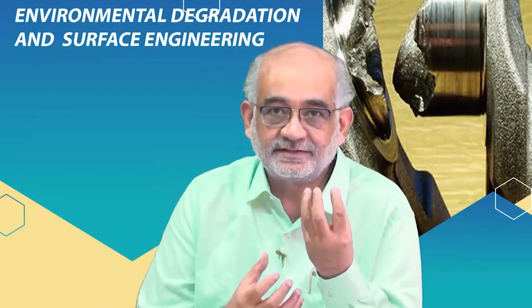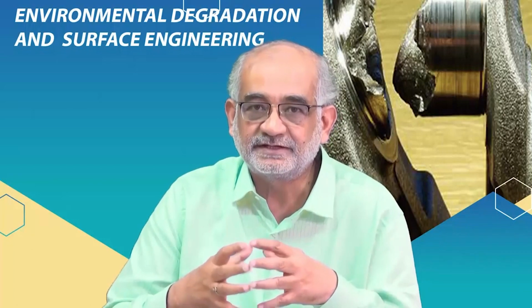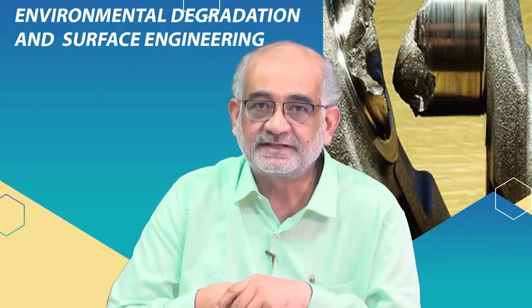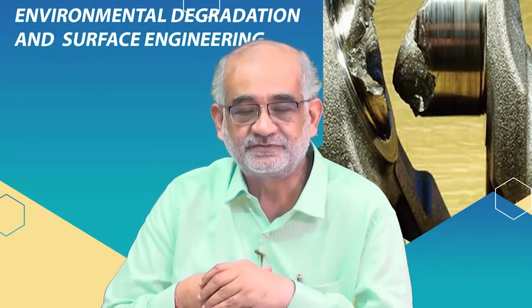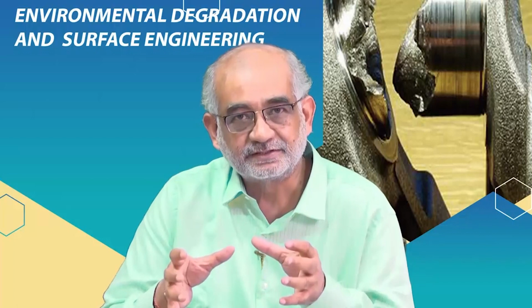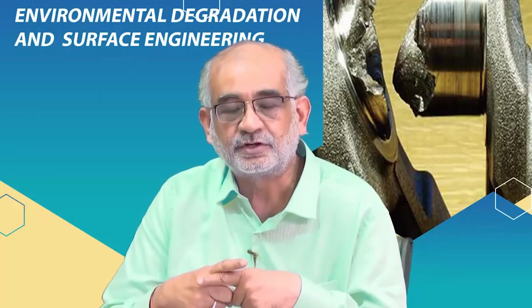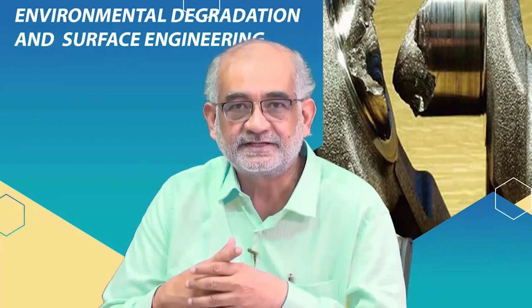So there the structure, the pole has to be of metal because you require certain engineering properties like strength and toughness and durability and so on, and also ease of fabricability. So you cannot create a complete tower out of porcelain. So you create a tower out of metal, but you can't afford to allow the conducting wire to come directly in contact with the tower, which is of metal, because then people touching it will get electrocuted.